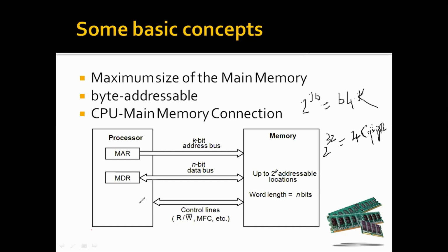Whereas when you come to the memory data register, we have to save the data into the data bus, and also from the data bus save it over here. So the memory address register has the address lines, and the data register has the data lines. These two are the most important parts to access data from one to the other.